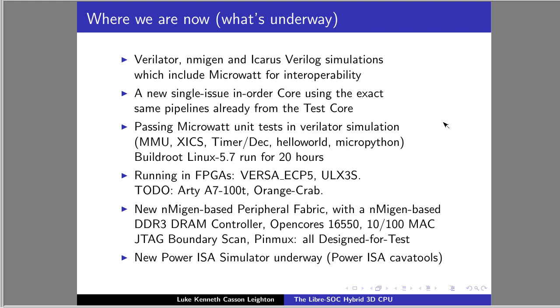So what you do is you put those 1,000 or 2,000 pins worth of peripherals through a pin multiplexer, as I'll call it, PinMux, out to 200 or 300 pins. And what that does is it saves an awful lot of money on packaging and makes the package more reliable. You get much higher yields. But now you've got some complexity in there that you've actually got to test, all those pins and the peripherals, and that's what we will be doing with the JTAG boundary scan.